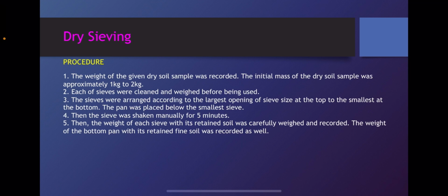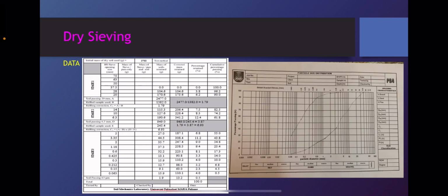Then the sieves were shaken manually for 5 minutes. Then the weight of each sieve with its retained soil was carefully weighed and recorded. The weight of the bottom pan with its retained fine soil was recorded as well. So this is the data of my experiment.